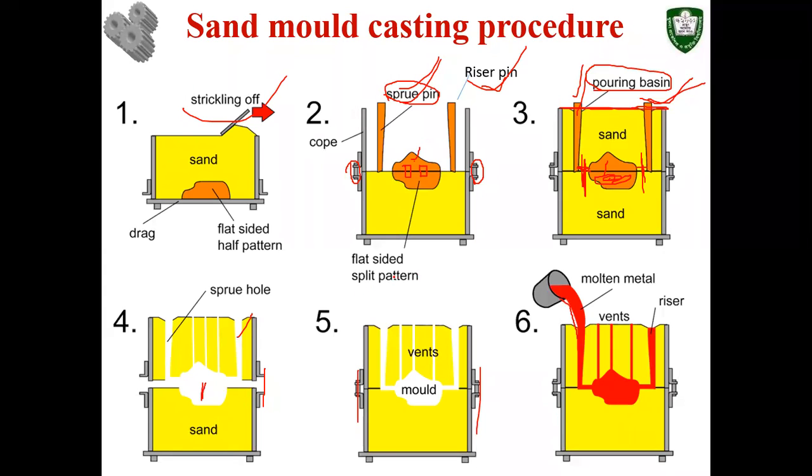Okay, you might have a question like, why these white regions in here? In this case, the riser does not completely serve to remove the air, because once the material is filled up to that position, the riser gets blocked. That air is trapped in this region. How do we remove that trapped air? We need to use vents.